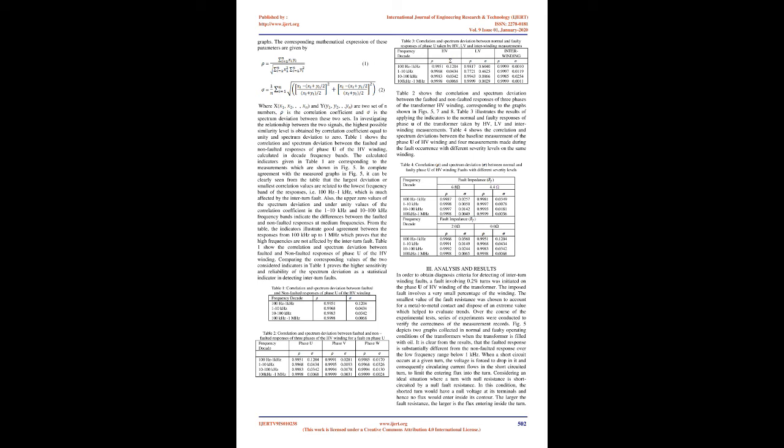Through these studies, it was found that measuring voltage gain across the HV winding of the transformer, keeping all HV and LV non-tested terminals floating, offers greater sensitivity and ability in fault detection, owing to providing more resonance points and also effectively taking into account the core effects at lower frequencies.